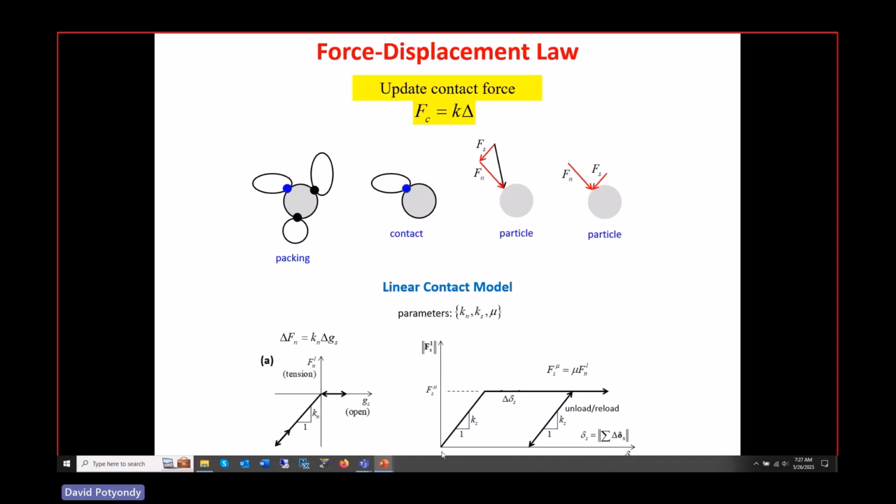So think of this. If I start making a shear motion, I start going up linearly with the stiffness Ks. Again, just like your skin, it loads up with a shear stiffness. Another thing is in almost all cases for almost all materials, the shear stiffness is less than the normal stiffness. In the models we're going to build, usually it'll be about half of the normal stiffness.